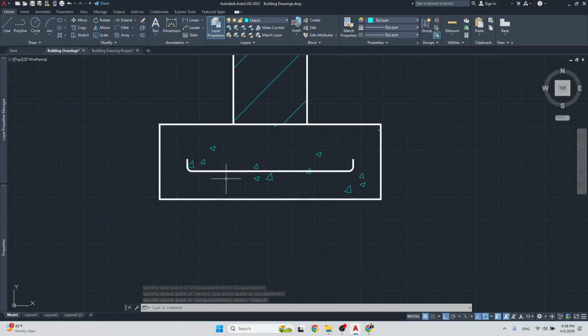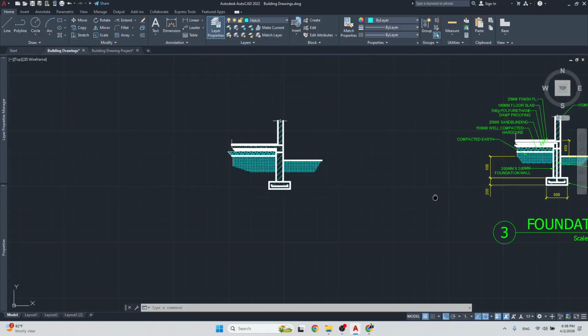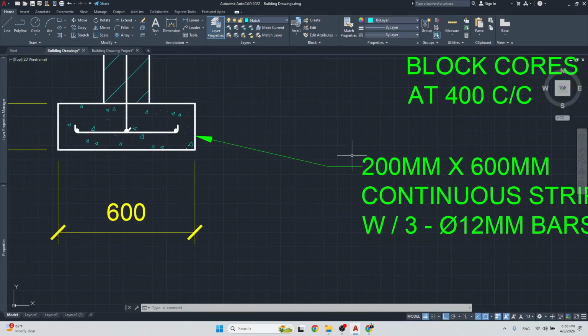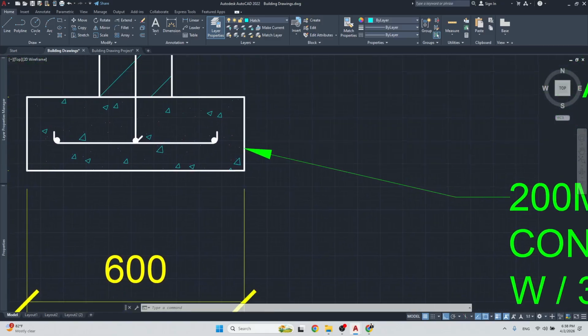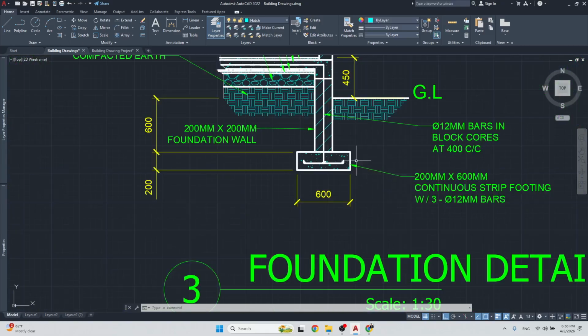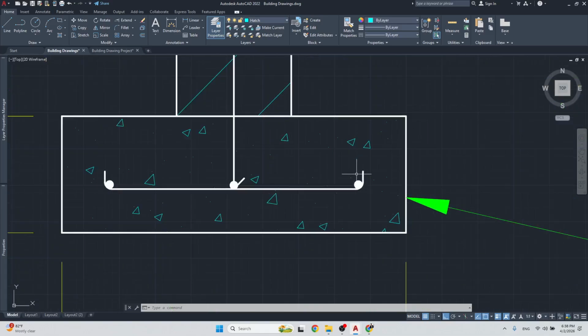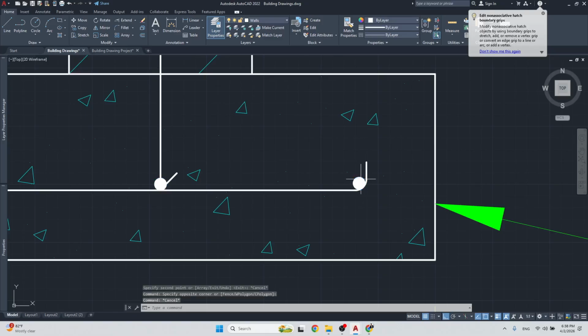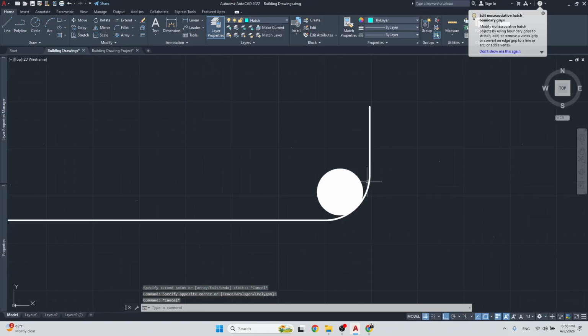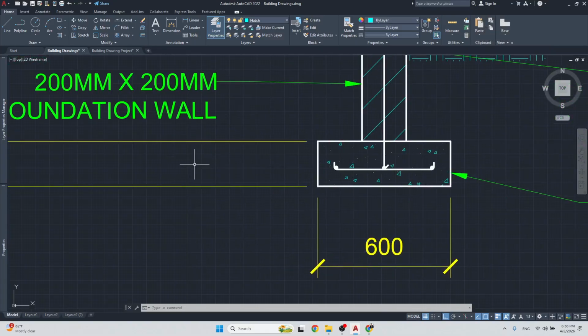All right. And then the reason why I use 12 for the fillet is because 12 millimeters is because the steel bars inside are going to be 12 millimeter in diameter. So it just matches this curve of the steel that's there. That's why I'm using 12.